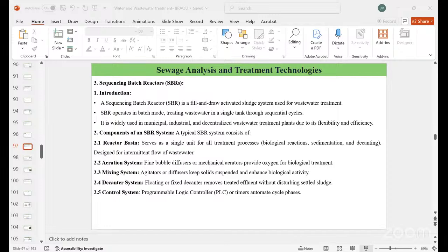The key considerations we have to look into in this process start with pathogen inactivation. Whichever disinfection process the water undergoes, the primary goal is to achieve a sufficient level of pathogen inactivation in order to meet regulatory compliance. Then the formation of disinfection byproducts, that is DBPs, is crucial for protecting public health. DBPs might either be carcinogenic or harmless, but we have to take care that only minimal chlorine injection or minimal oxidation occurs.